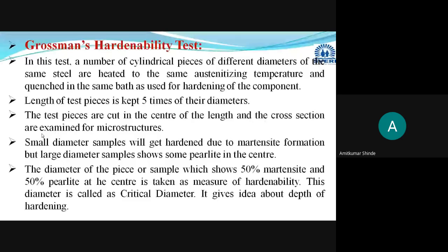Okay, different diameters and different lengths, and we are going to repeat the same procedure, that is heating that steel sample and completing its transformation to homogeneous austenite, that is austenitized steel, and then cooling it in the same kind of arrangement, with one end fixed. Now, the same process is repeated by preparing different specimens with different diameters and different lengths.